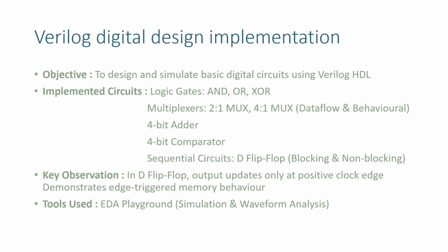One of the initial tasks was implementation and simulation of various digital circuits using Verilog HDL. First, I designed basic logic gates like AND, OR, and XOR. Then I worked on multiplexers, including 2x1 and 4x1 mux, using both data flow and behavioral modeling. Next, I implemented a 4-bit combinational adder and a 4-bit comparator to perform arithmetic and comparison operations.